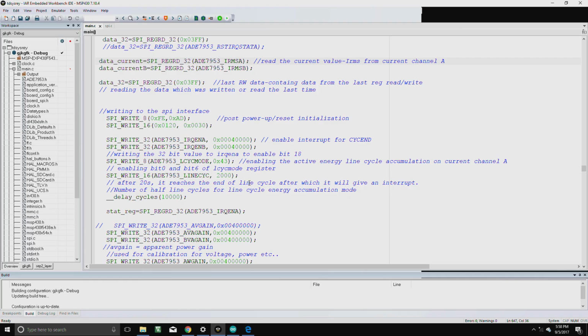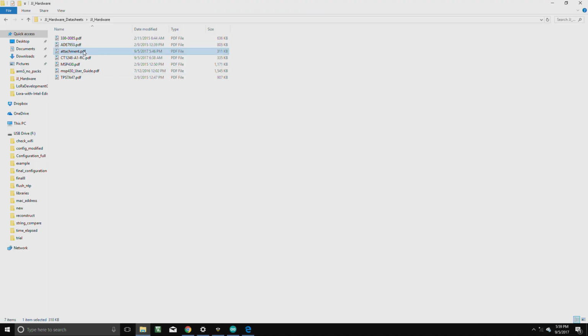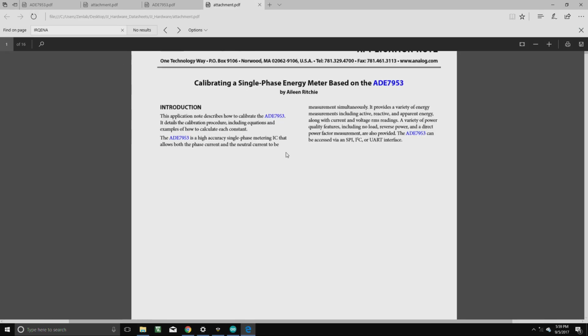Let me point you to the top extreme left here, which says that this debugger that we are using, the software environment tool, indeed is the IAR embedded workbench IDE for MSP 430. Your problem does not end here. Actually, in order to get accurate values and try to meet the data sheet requirements, you also have to do calibration of some of the registers. That again is another document. So, now let us go and open up that document and read the starting part of that document.